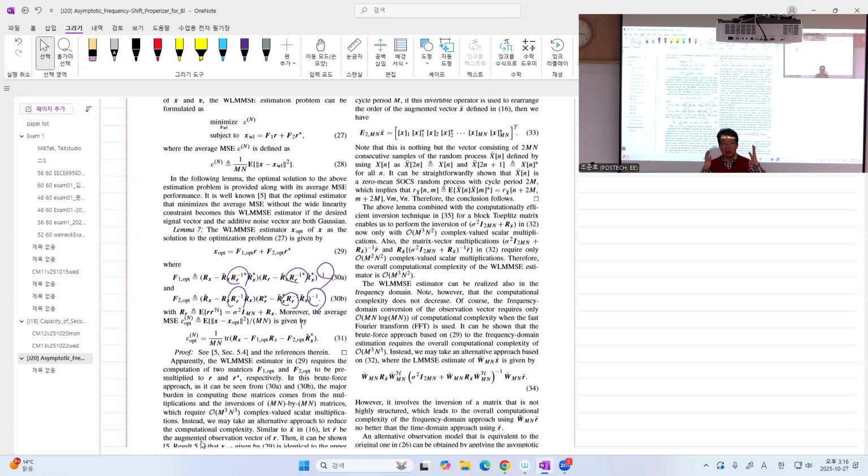But actually, when we receive the signal, we have some unknown rotation of the constellation. In that case, what will happen if you take the real part and if you take the imaginary part? All these binary decomposed components will appear, not only in the real part, but also in the imaginary part, and they just have very complicated mapping rules. So that does not work. That's one of the reasons why people want to keep the complex valued signal.